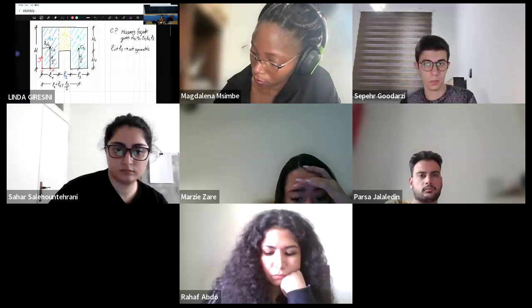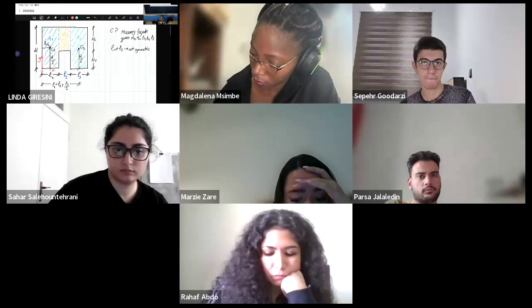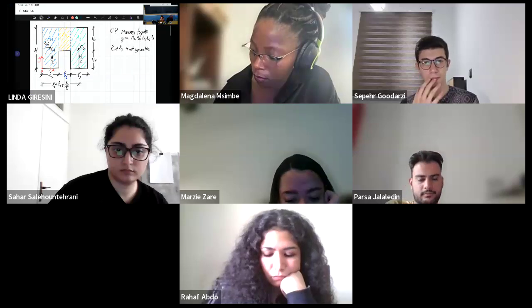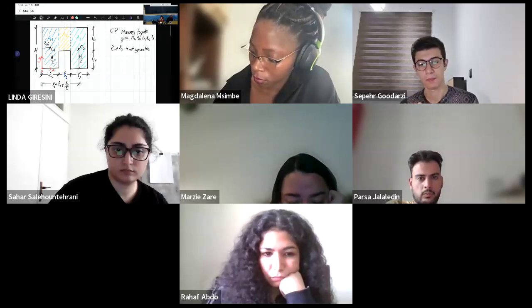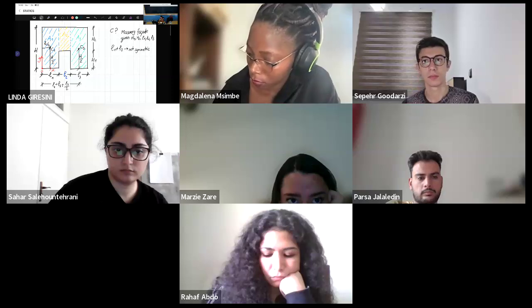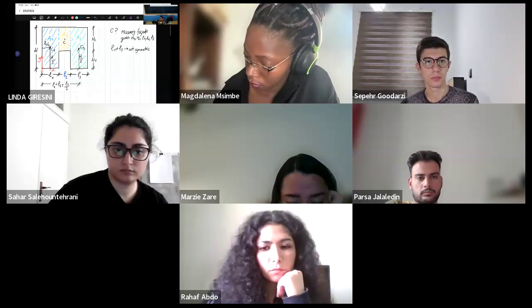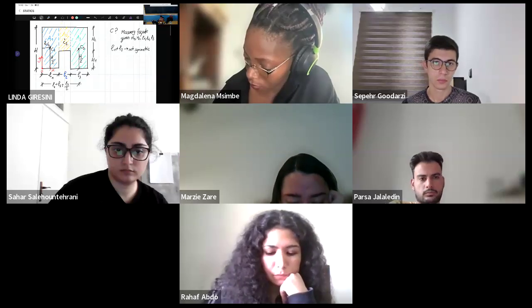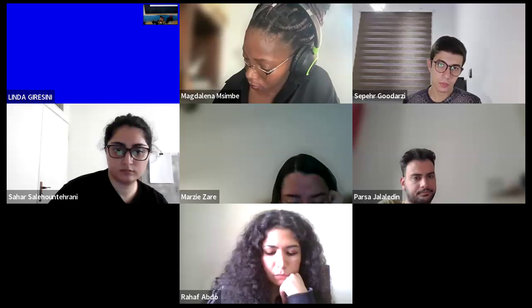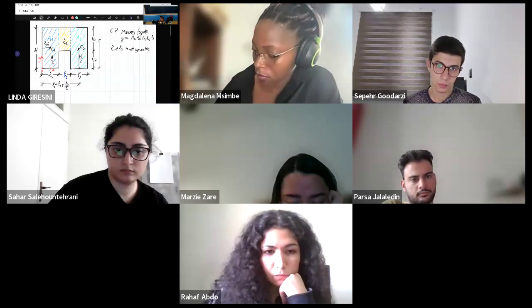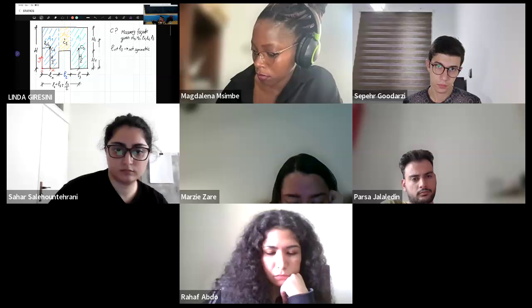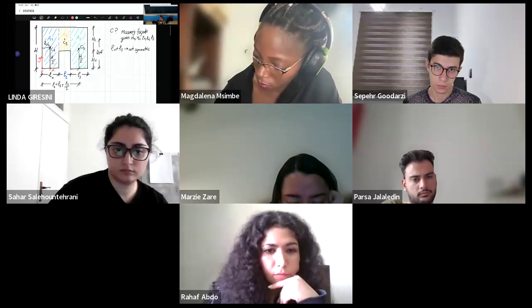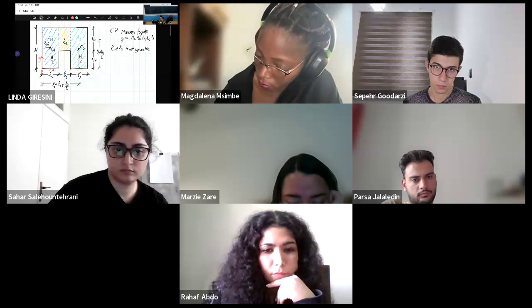So we already know the centroids of these rectangular areas. We don't need to make integrals or difficult stuff. We know already. And the same will be for C2. For example, the height of C2 will be what? Perfect. H1 plus H2 divided by 2.